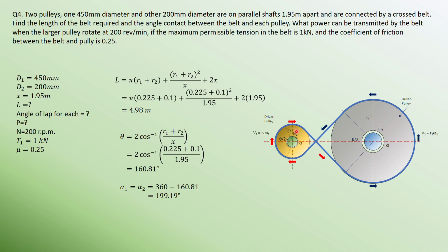Here it is rotating in the clockwise direction, so you will be exerting a pull at this point. So this side of the belt will be the tight side, and then it delivers to the other side. This should be your slack side. Again, it depends on the direction of rotation of the pulley, please.